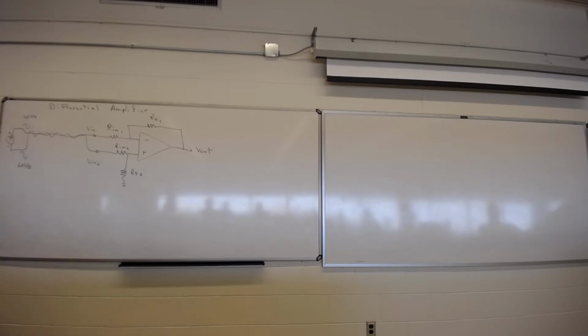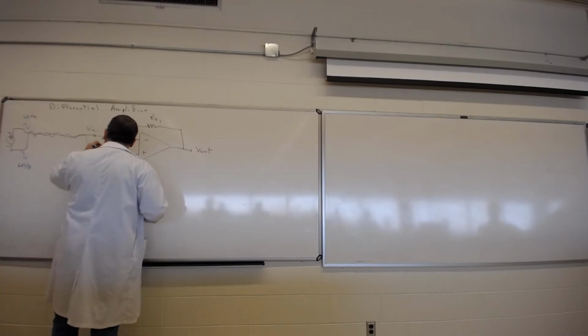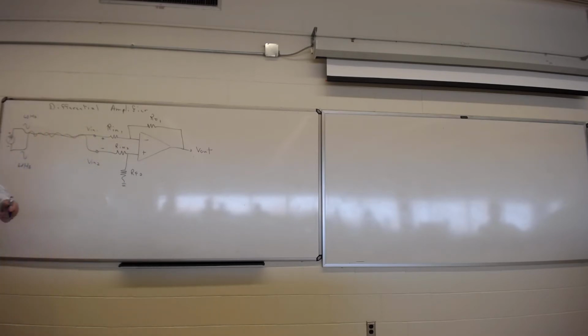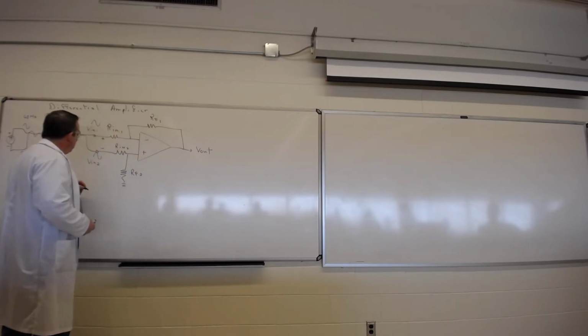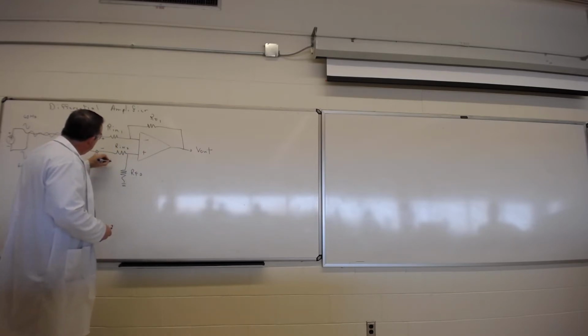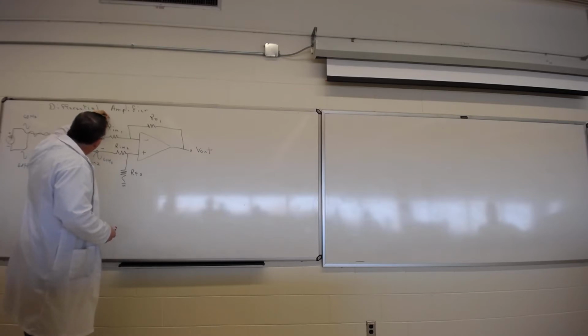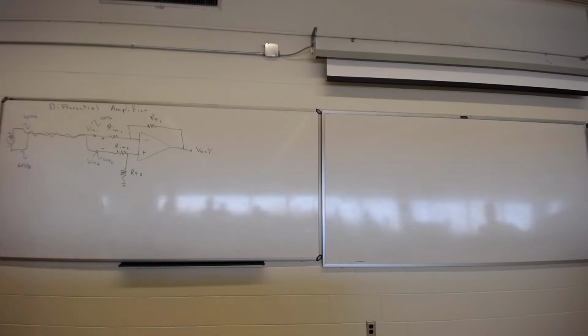So that noise hops onto your wires. So you've got thousands of feet of wire going to the sensor, and it's picking up noise. The nice thing about it, the noise is being picked up on both wires. Okay? So when it gets over here, not only do you have the plus or minus voltage from the sensor, but you've also got 60 hertz that arrives with it. 60 hertz here. Which is not so desirable. And in some cases, there could be more noise than there is signal.